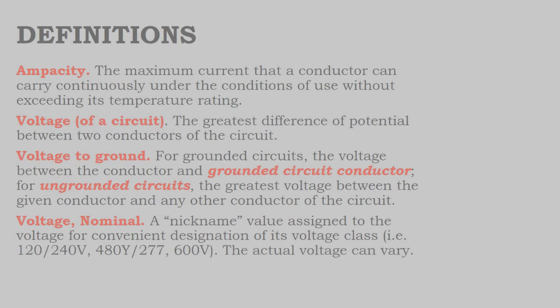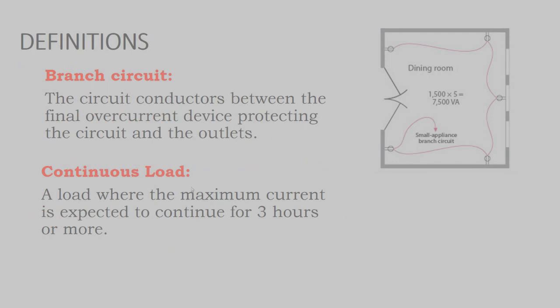And then you also have to consider your operating conditions as well. That might mean that a solar array is going to be operating at 30 volts on its spec sheet, and that would be considered the nominal voltage. But its maximum voltage may be something different. Its maximum voltage may be a function of temperature. And so we have to apply temperature correction factors before we get into our design to make sure those conductors don't burn up.